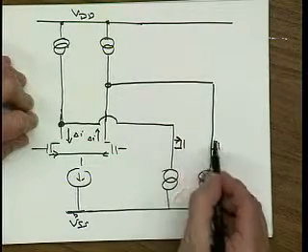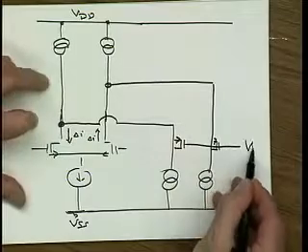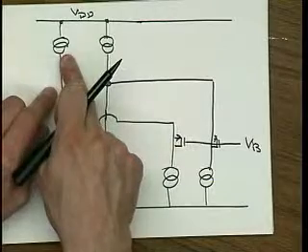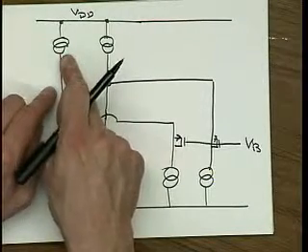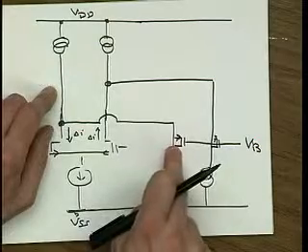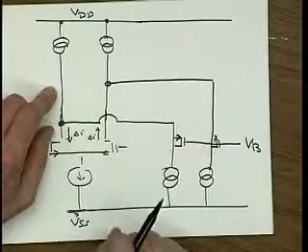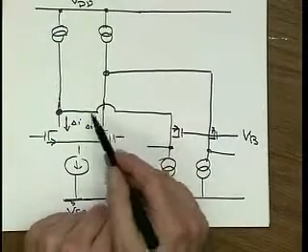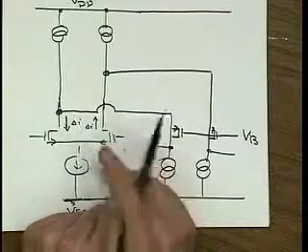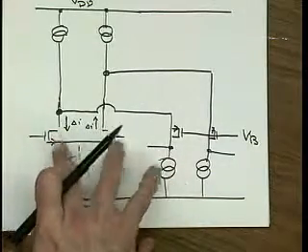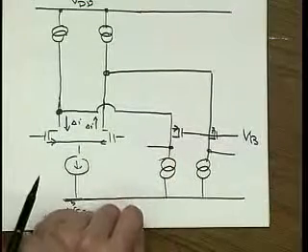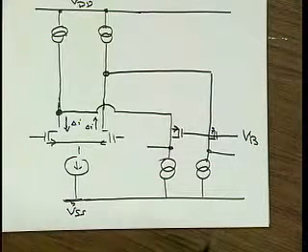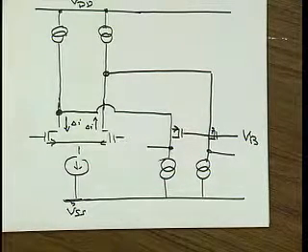So they shouldn't be shorted, right? That current here sees the very high impedance of the current sources. High impedance means high resistance. It doesn't like to go there. It sees the much lower impedance of the cascode, and therefore it moves over here. So that's now the output of my amplifier, and so the differential current, the current mismatch produced by the differential pair, simply flows into these two nodes. Well, these two nodes see current sources, and consequently this produces a large voltage gain at those nodes.